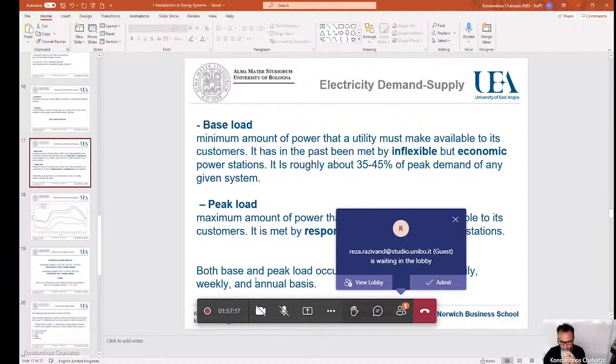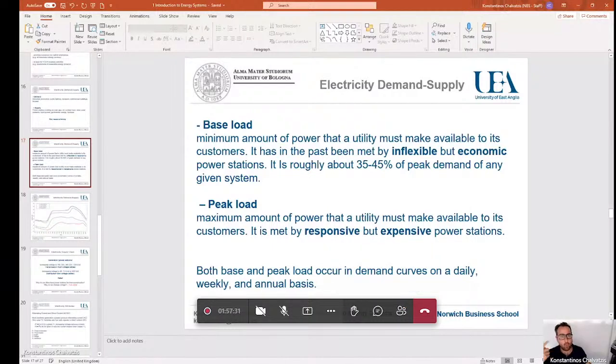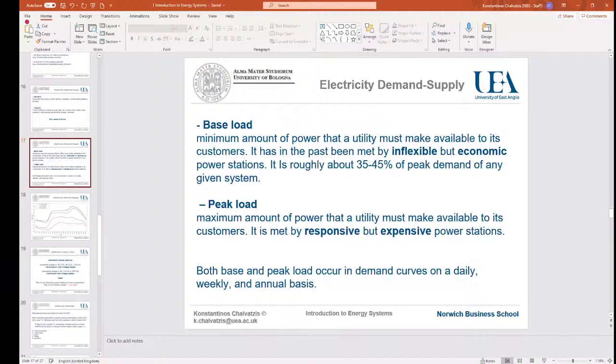Have a think. For example, refrigerators, fridges. Correct. These appliances are always there. From an individual point of view, if you're thinking of one refrigerator at your house, it does not consume energy continuously; it switches on and off itself. It has a thermostat. When the temperature inside the fridge rises above a certain point, then the compressor behind the fridge starts working and it consumes electricity. But if you factor in 1 million fridges around the country, then the total consumption that they have at any given time is a type of consumption that never goes away.